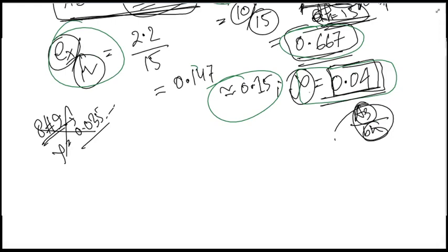So for that, let's focus on the graph. This is the graph, a very well-known graph. There are different graphs, as you can see. This is the initial graph. You will have to fix the pattern, which pattern of columns we have taken. So this is our concern graph. See here, you can see fc prime 4 ksi, fy 60 ksi, and gamma equals 0.6.